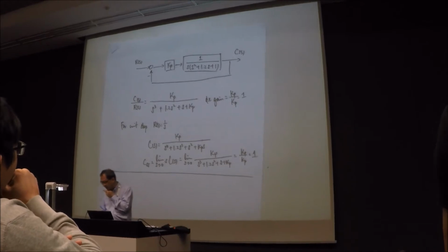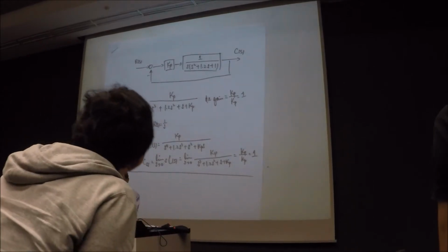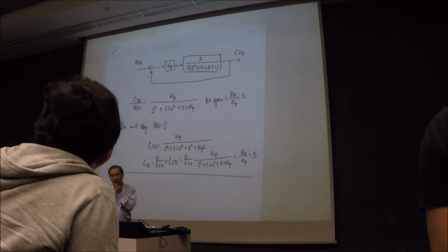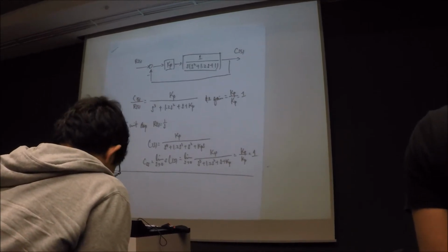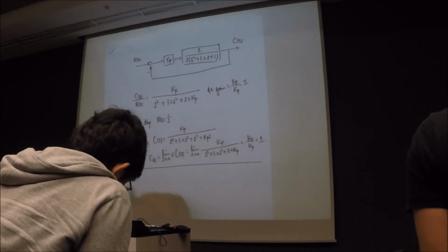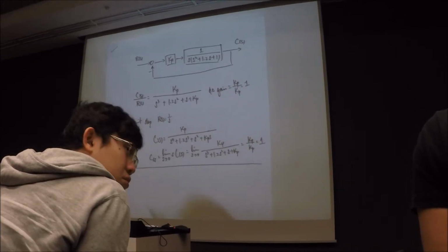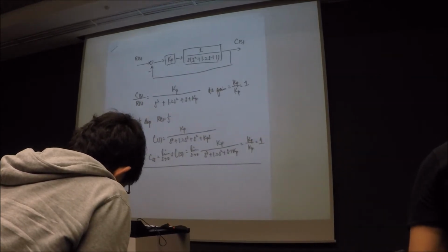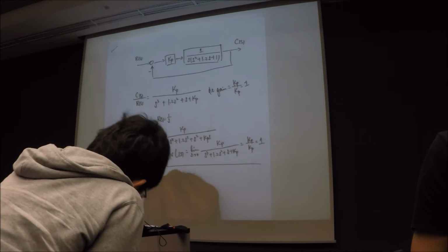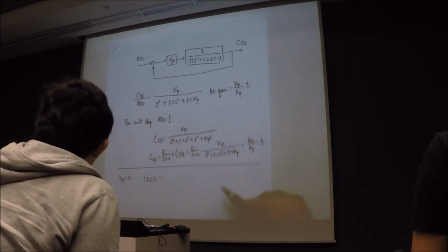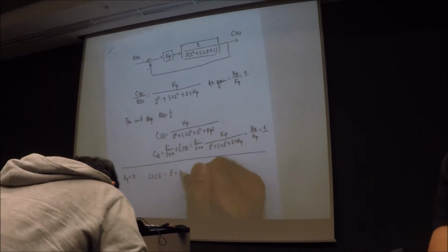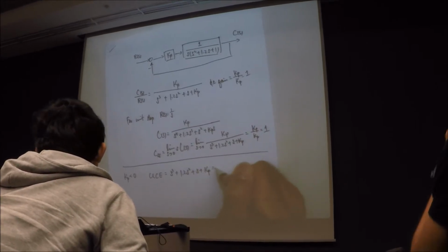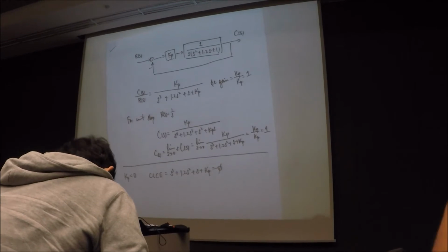So in this case, we were asked to study the effect on the stability of the system of a negative value of your Kp. That means if Kp is less than 0, what happens? So go back, what is your closed loop characteristic equation? Your closed loop characteristic equation is going to be s cubed plus 1.2 s squared plus s plus Kp equal to 0. Okay?